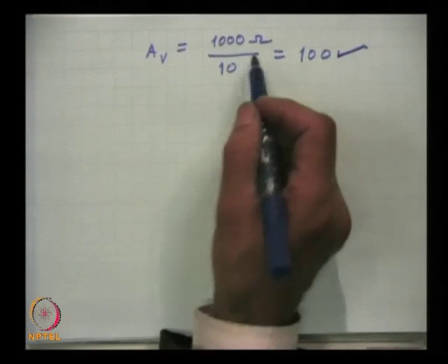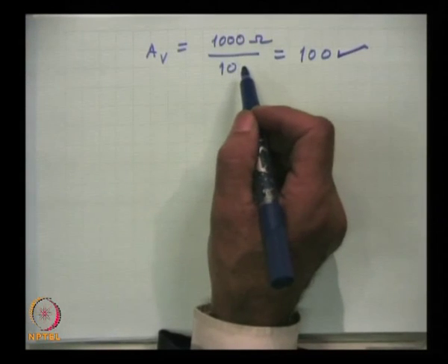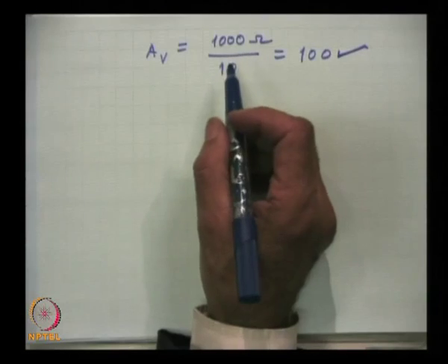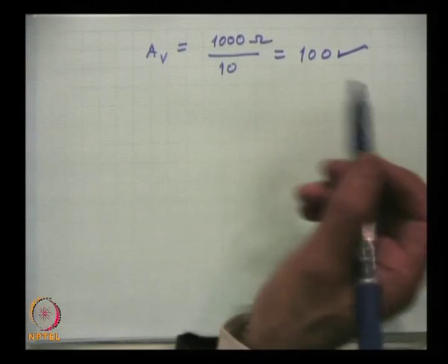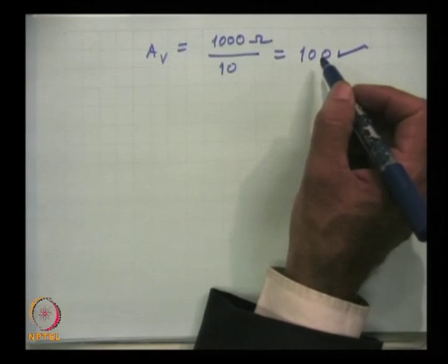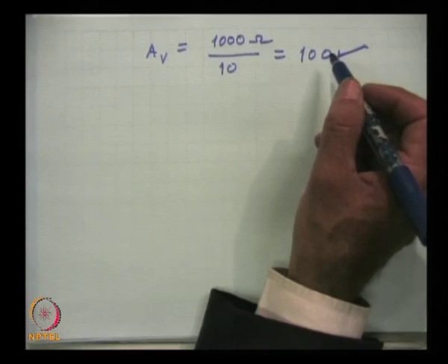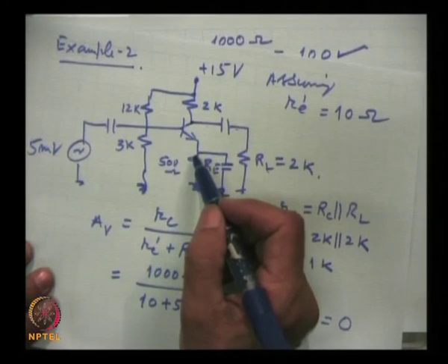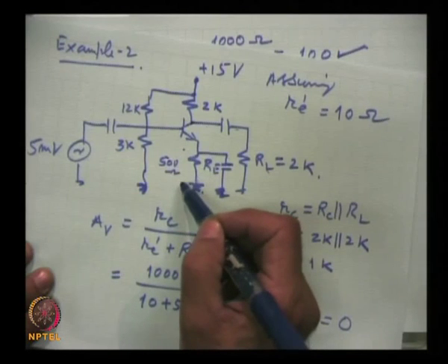Now, these are two extremes, the voltage gain 2, the voltage gain 100. This will be unstable because the dynamic resistance is temperature sensitive. So, we can make a best compromise and we can settle, for example, at a gain of 60, 70, 80 by breaking this 500 into two resistances, 100 and 400.